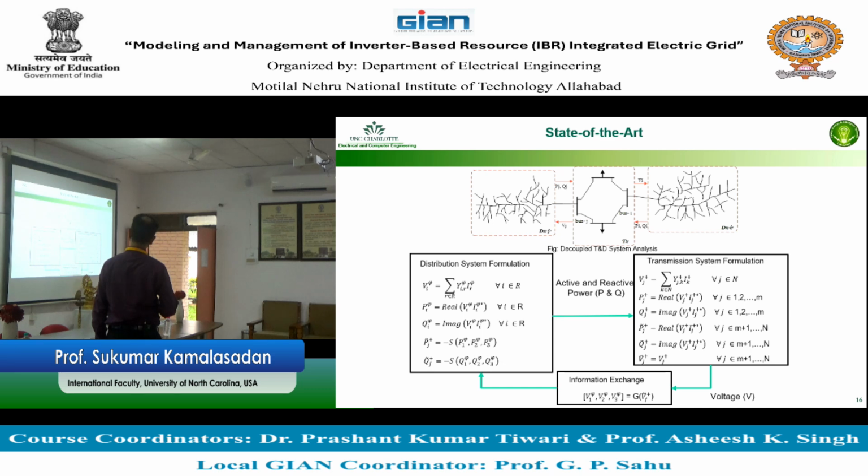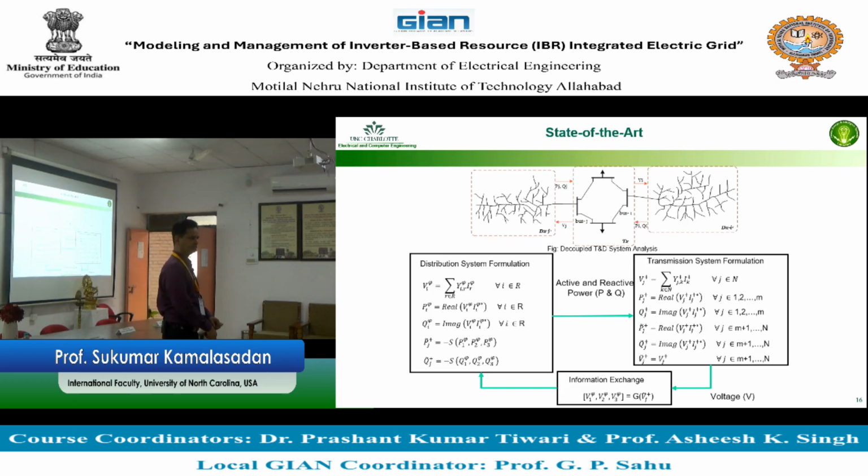So what you do is you exchange the power from the distribution system to the transmission system and run the transmission system model. After you exchange that power, you run the transmission system, get the voltage at the distribution system head end, and run the distribution system model back again. This is what we call the decoupled power flow approach, which means you are running them in tandem. You are not running or developing anything together. You run one, you get the result, and then you run the other.